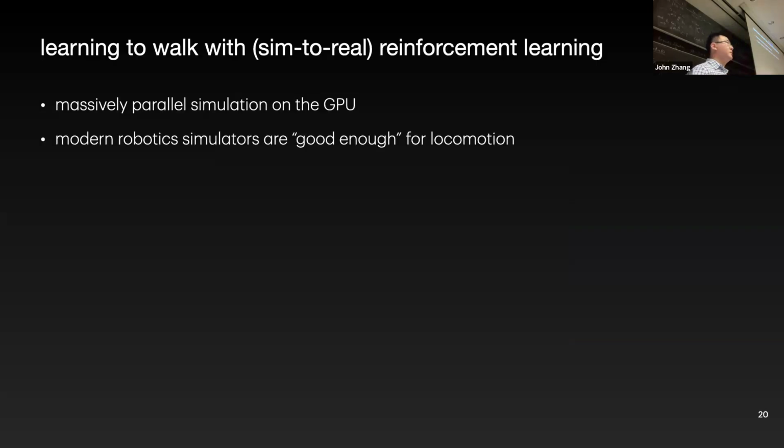And the other thing I would say that made RL work is that people have mastered the art of having good enough physics for these locomotion tasks, and also generating large sets of data that can satisfy RL's data-hungry appetite. In particular, the point contact to surface simulation is fairly good. It doesn't capture all of the physics, but it's good enough for a robot to walk around, and can even be quite robust sometimes. But for a lot of the manipulation settings, I would say the simulators today are not quite good enough, and people are still actively working on those things.